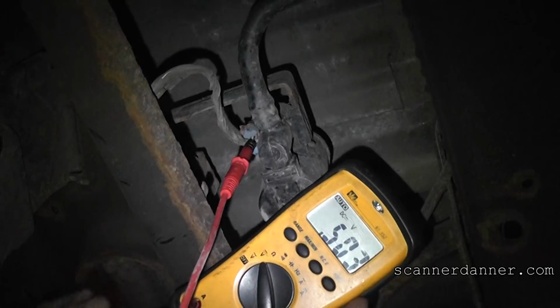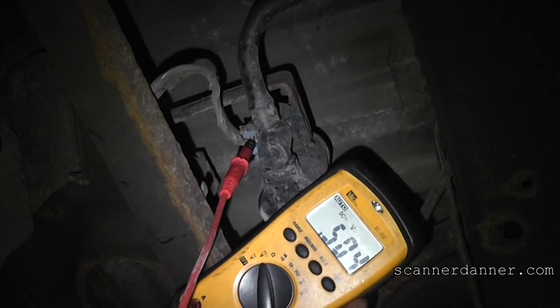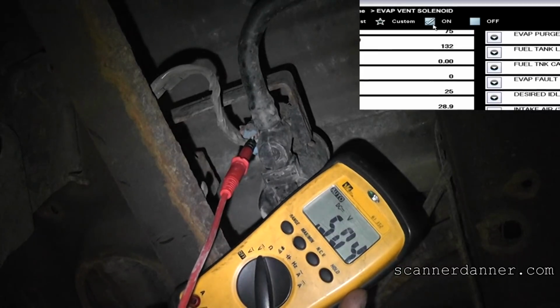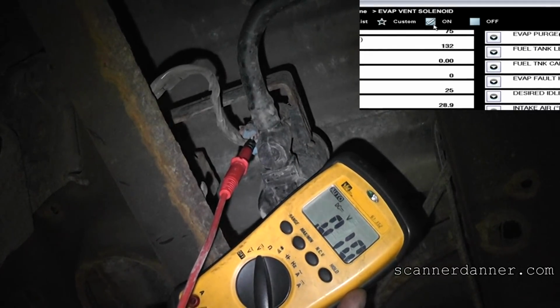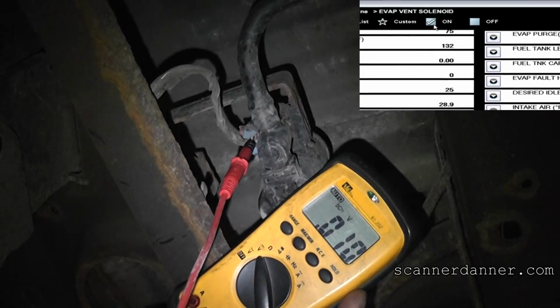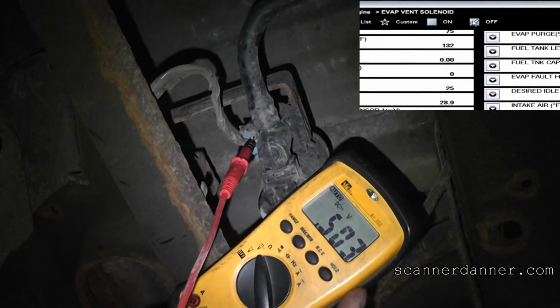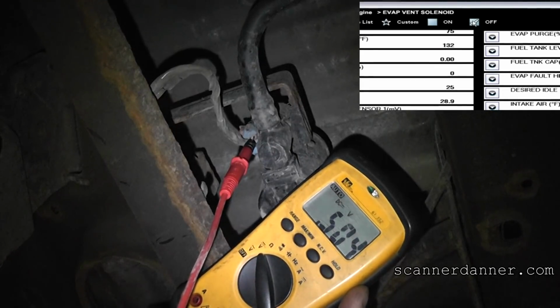So Bell, you don't have that solenoid on right now, do you? No. With the scanner. Can you turn it on for me so I can watch this? You see it drop, guys? Yep. So it looks like the driver's functional. Turn it off. It went to 500. I don't like that 500 millivolts. That's way too low. High resistance for sure.